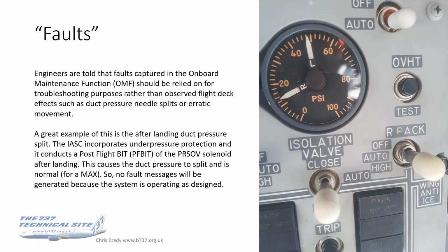And I guess what it comes down to is knowing what is normal. You now know, because I've told you, that it is normal after landing to see this duct pressure split whilst this check is being conducted. If you know that's normal, then you won't report it to the engineers. If you didn't know it was normal, then you would. And I guess where Boeing were coming from was that they were getting a lot of reports of this, probably because they didn't document that this was going to happen, which, you know, that's on Boeing.